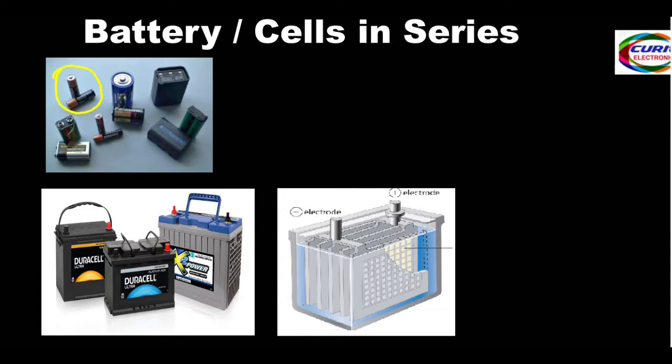And if you see here, these are the lead acid battery. That means usually we will get a voltage of 12 volt. It's not exactly 12 volt because when a cell is fully charged, the voltage varies, and when it discharges also, voltage varies. So this 12 volt lead acid battery voltage varies from 12 volt to 13.8 volt. When it discharges, it goes to 11 volt.